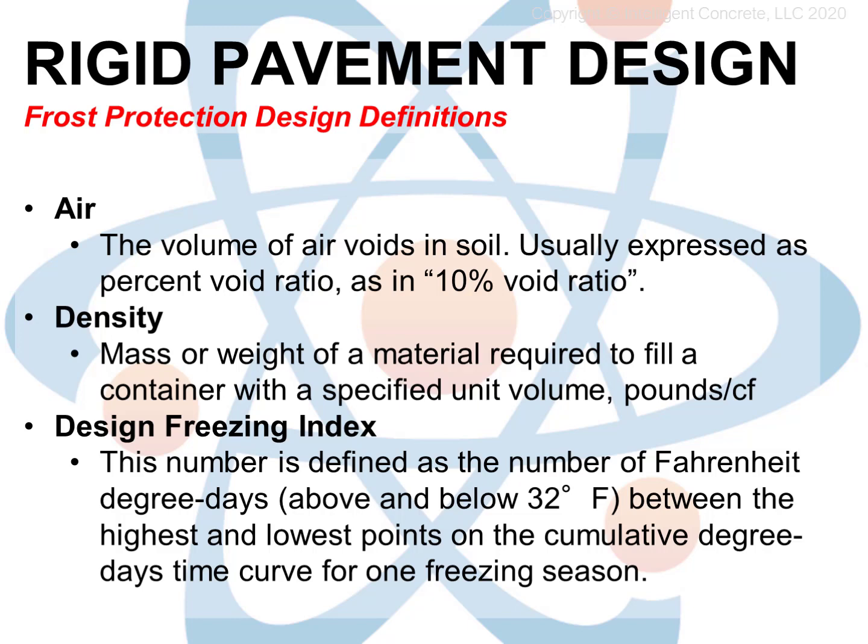The design freezing index is a means to quantify the overall hazard presented by freezing conditions. It's based on how many hours of the year the air is below freezing. 1 hour at 1 degree below freezing carries a certain value in the design freezing index calculation. 24 hours at 1 degree below freezing is the same as 1 hour at 24 degrees below freezing, and that is known as 1 degree day. All this time and temperature data are aggregated into a single theoretical number of degree days for a particular location, and it is used as part of a frost-protected pavement design.